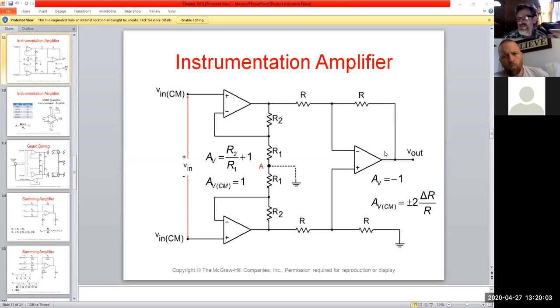So what does that mean? Again, you'll get the signal, but it'll be a 180-degree change. Always look at that when we're looking at op amps. The minute we see our AV is -1, that means whatever our input is, we're literally going to flip that by a cycle, okay? So you'll get that 180-degree shift to make it a negative.